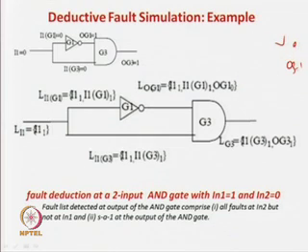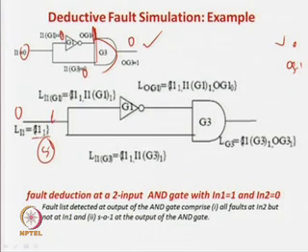So let us see. We have taken another example here. This is an inverter and so on. We put a 0 in the input. If it is a 0, you know that this input is 0. So this is going to be 1, this is 0, and the answer is 0. Now the input to the AND gate here is 1 0. So let us study the rule. You apply a 0 over here, so a stuck-at-1 fault is detected at this net. It is this one.